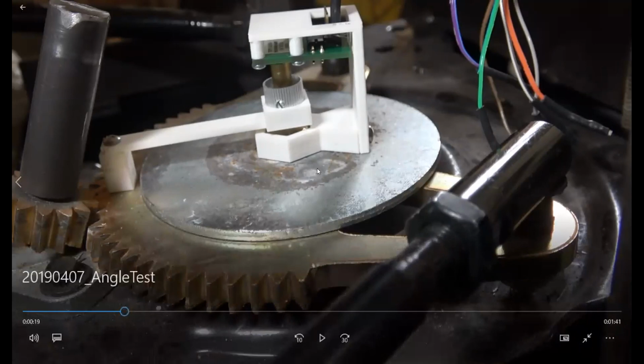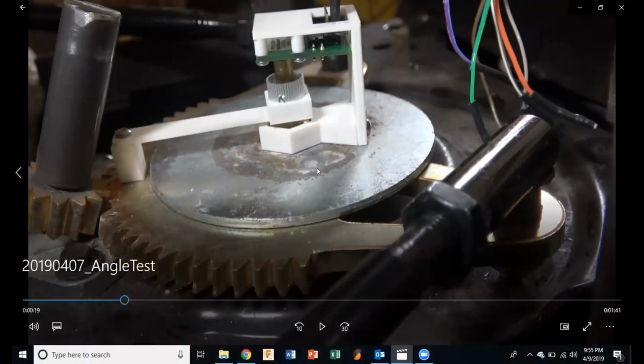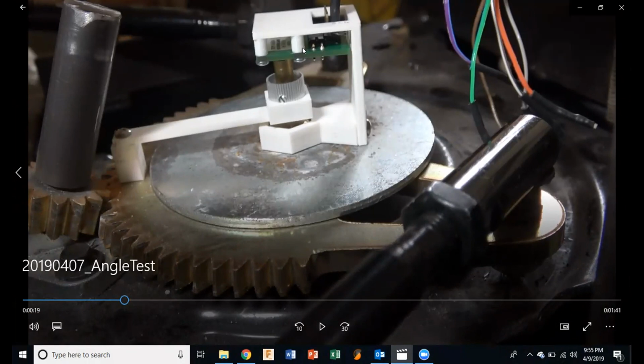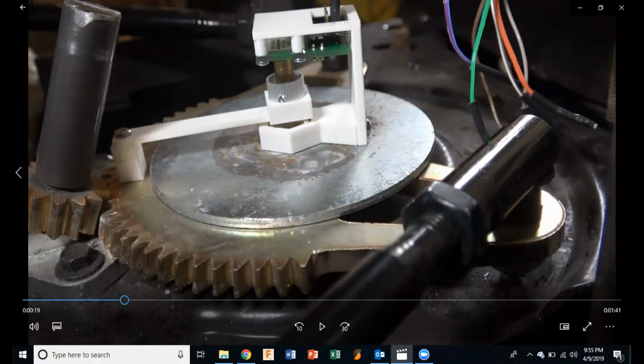Were you planning to connect that board to your Teensy or to your RPi? The way I was going to follow Matt's lead, he's feeding this signal into his Teensy. Okay, because in order to do closed loop steering, you want to feed that into the Teensy, and then it controls the steering motor, so it can all do that independently of the RPi. I didn't know if you're trying to connect it directly to the RPi, but I think the Teensy is where you want to go with that.